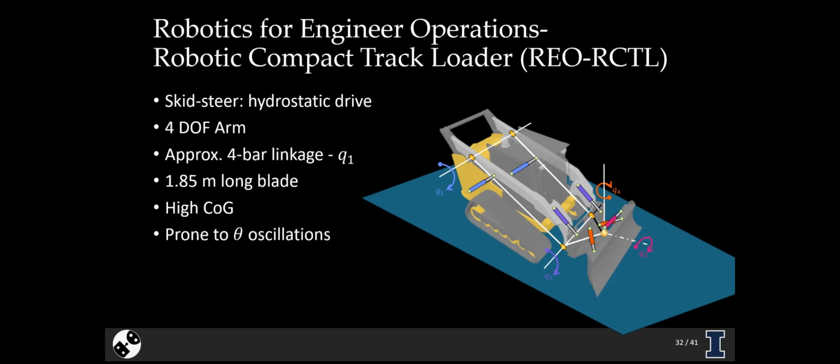And then the second joint here is this pitch axis. So the blade is able to kind of pitch up and down, which also affects the height of the blade off of the surface. And then the third axis is the blade roll. So you can actually change the roll side to side of the blade in order to deal with varying terrain rolls as well. And then the blade can be yawed to do kind of plowing operations, for example.